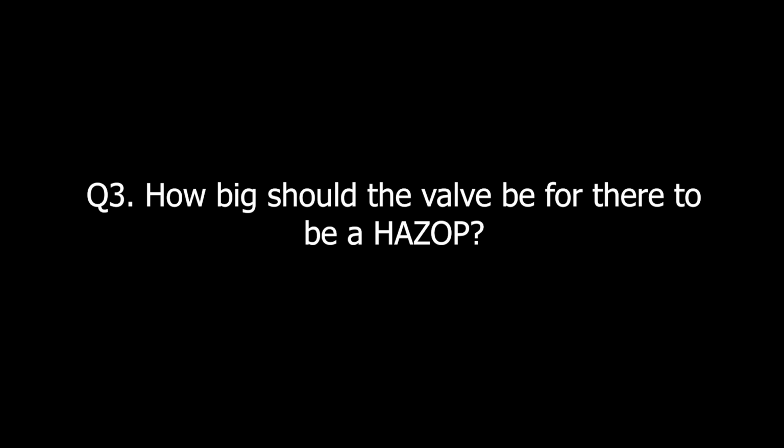So the size of the valve itself doesn't determine the HAZOP. It's the process parameters, and whether or not you have a standalone equipment package. That's what that was referring to. So it's not so much the size of the valve. Oh, okay, thank you very much.